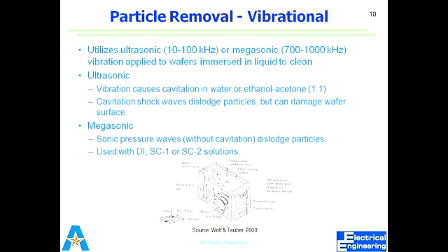But you know this thing that due to this cavitational shock, because it's just like a shock, because it collapses suddenly, the wafer surface can be damaged as well. So just to avoid this cavitation shock, what we do is go to higher frequencies. We go to megasonic frequencies.